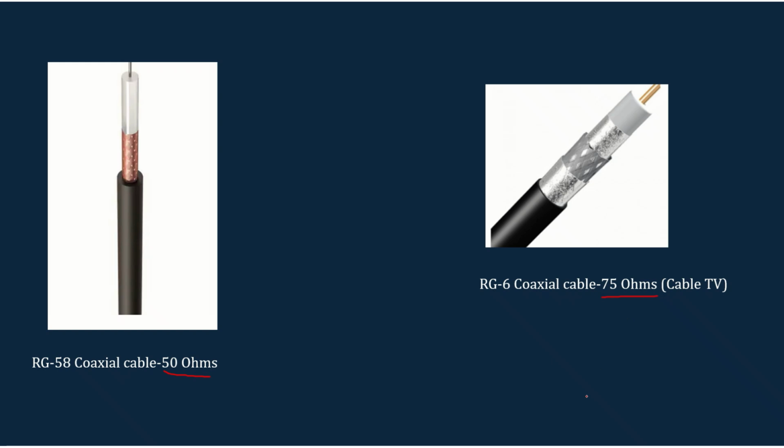If we are using the Smith chart for different impedances like 50 ohm and 75 ohm without normalizing, we may have to use different Smith charts, one for 50 ohm analysis and one for 75 ohm analysis. To avoid that, we can normalize the impedance.